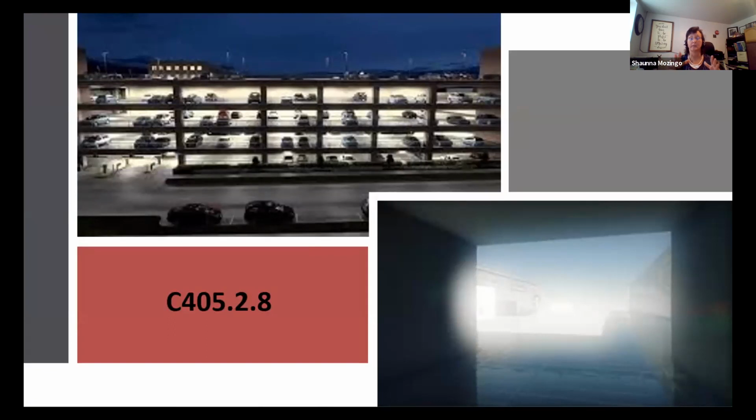And that's in lighting zones. So it's just like the warehouse spaces and the open office spaces. We're going to create zones, but these zones are no more than 3,600 square feet. So trying to cut those parking garages into smaller spaces so that we don't have lights on in the whole thing. If there's no activity in a 3,600 square foot area within 20 minutes, then those lights shut down by at least 30%. Not going to go off because we want to maintain some safety in there, but cuts them down by at least 30%.